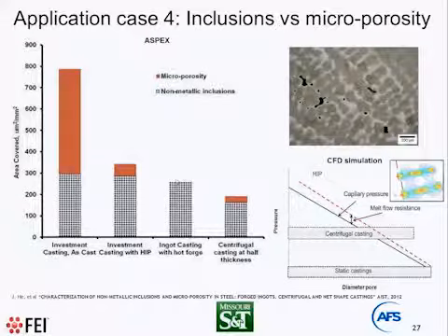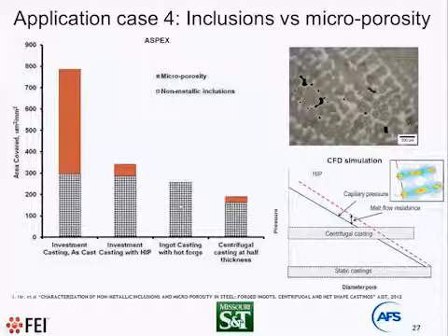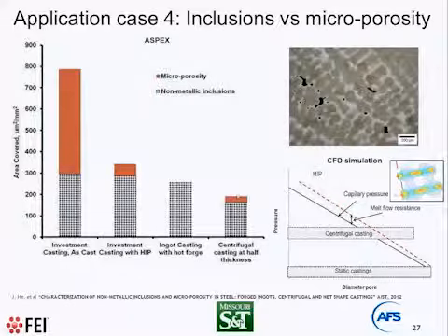Then we study ingot after hot forge. In hot forge, when we have flow of material during hot deformation, only in this case we can completely heal all pores. And look at here, centrifugal casting. So total amount of inclusion and porosity was less than ingot. Of course, centrifugal casting has some amount of pores, some amount of inclusion, but total amount was significantly less.